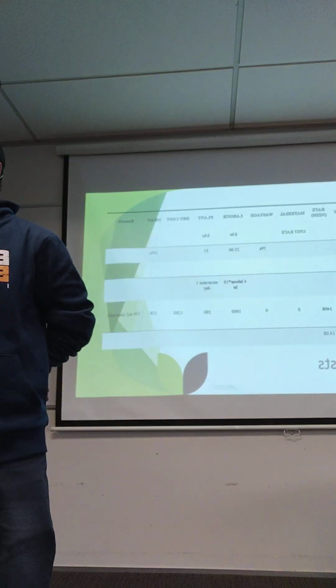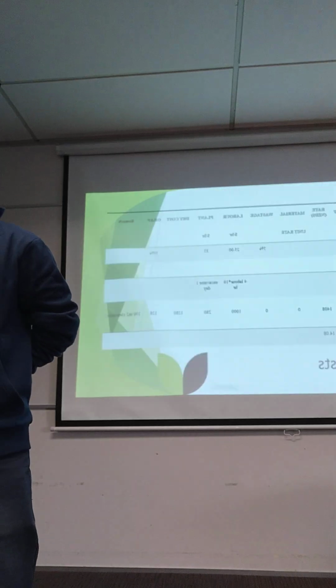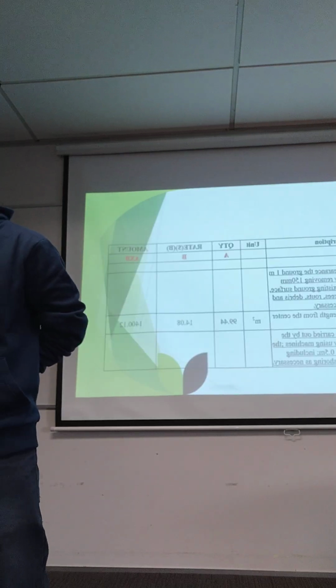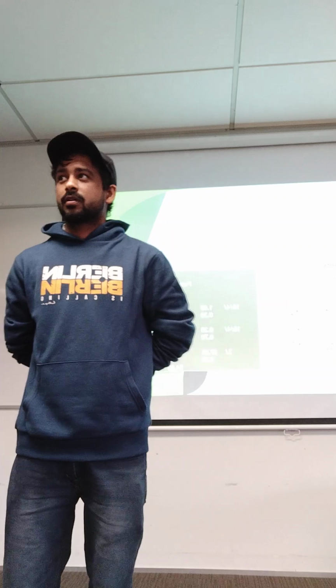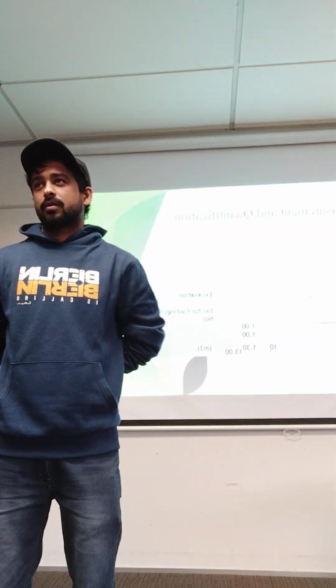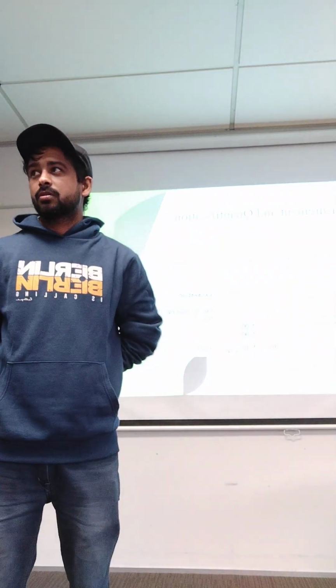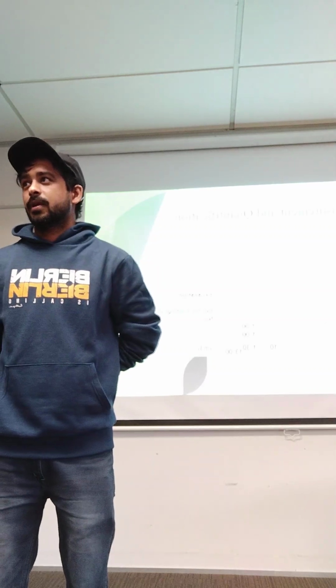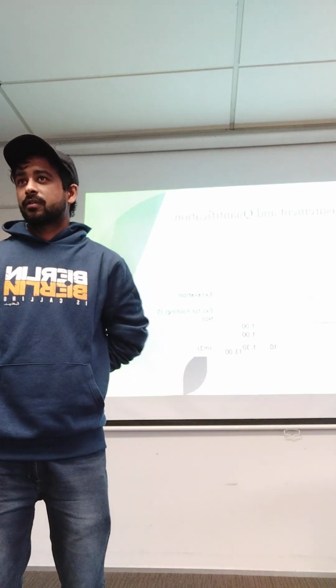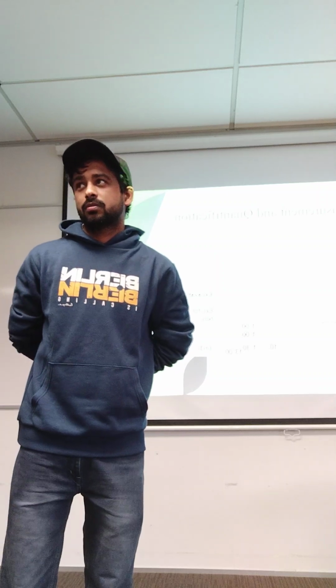What is disposal? Disposal is the material which is left over, soil mainly, from the excavation, which has to be cut away. Have you calculated the footing concrete volume? Yes, sir. How are you going to calculate? Concrete volume in meter cube, according to the drawing and as per the specification. What dimensions have to be taken? Length, breadth, and height of the concrete footing.